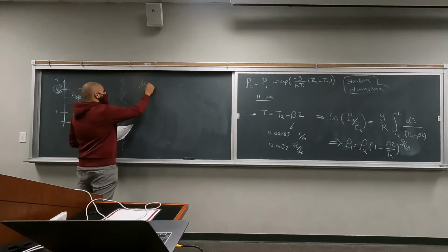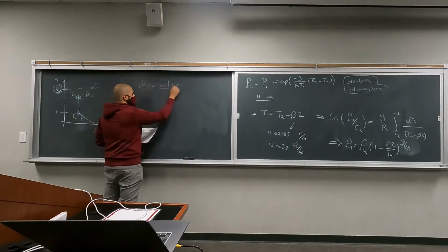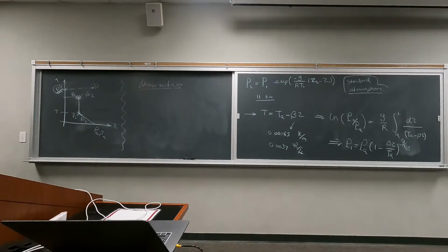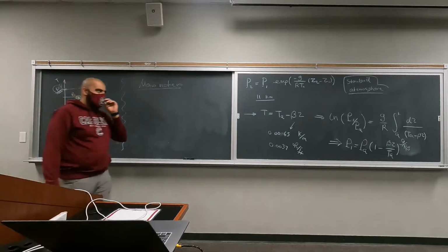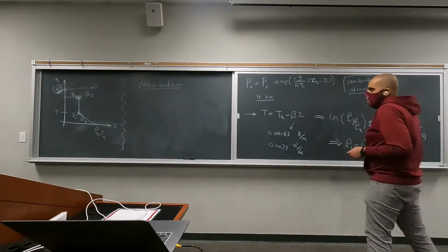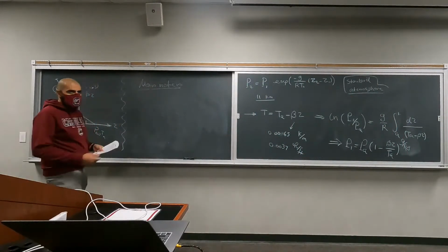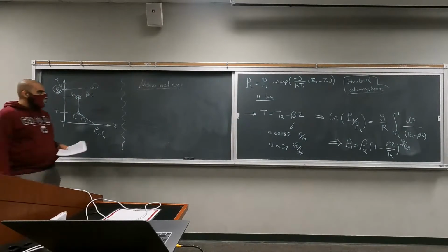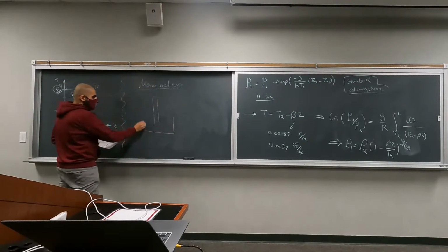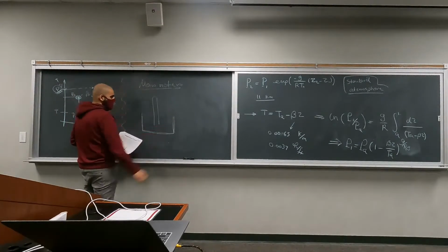One of the more famous pressure measurement devices is called the manometer. The manometer measures the pressure essentially using the same concept, right? The pressure is a function of height of a liquid or a fluid or gas in general, right? And we talked about the millimeters of mercury or water. This is what a regular, very simple manometer would look like.